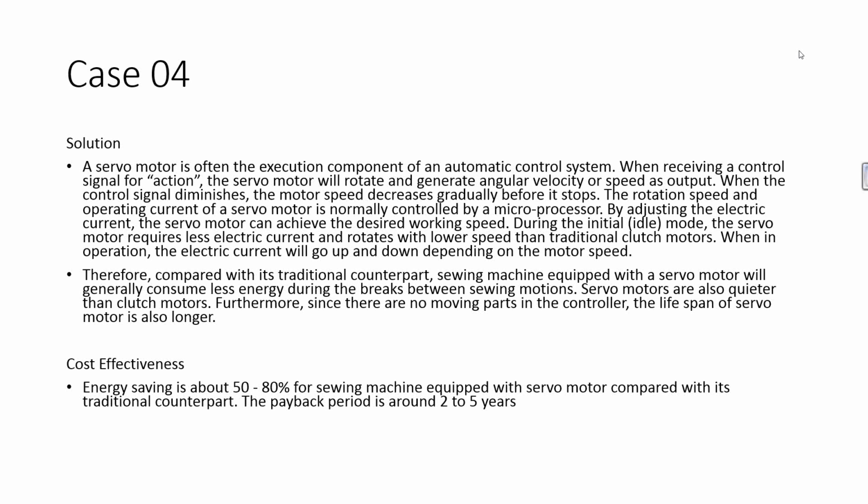The cost effectiveness. Energy saving is about 50 to 80% for sewing machine equipped with servo motor compared with its traditional counterpart. The payback period is around 2 to 5 years.